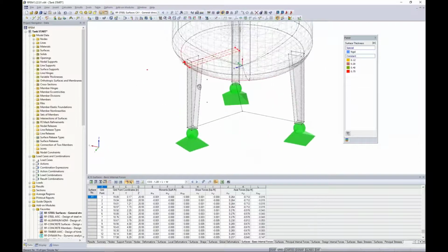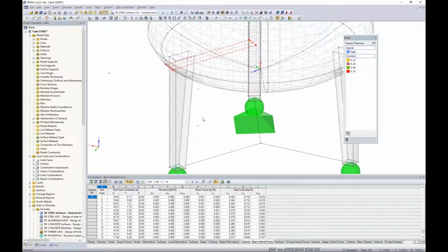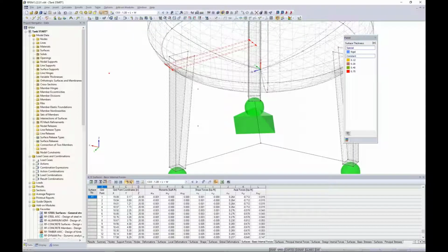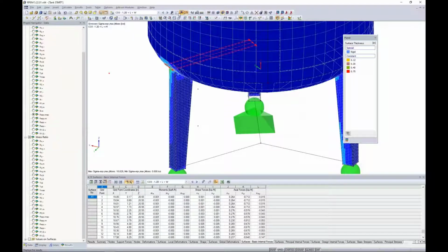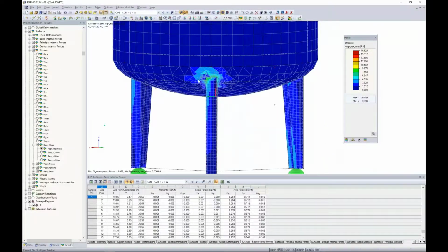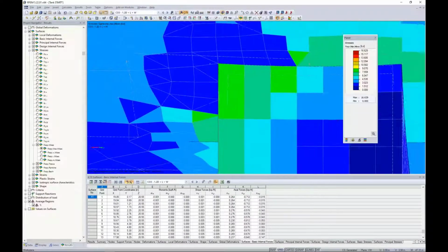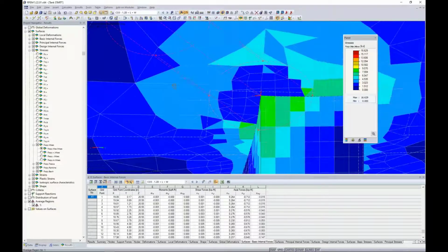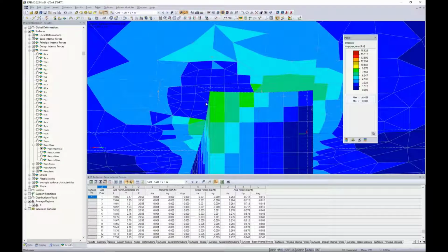So when I apply this average region, I'm going to view my results for load combination 3, and we can turn these on. And I'm going to kind of maneuver my model here and zoom into this point. I'm currently viewing my von Mises stresses, and notice that we no longer have these high peak forces here. So we're instead averaging out over this 2-inch diameter region for those von Mises stresses. Now, when you do apply average regions, you have a new checkbox here in your results where you can turn on and off the average region.